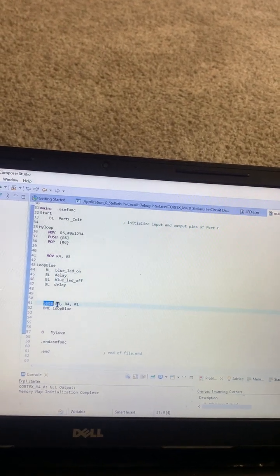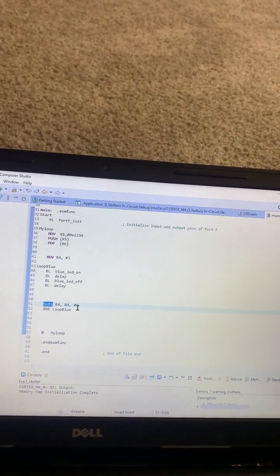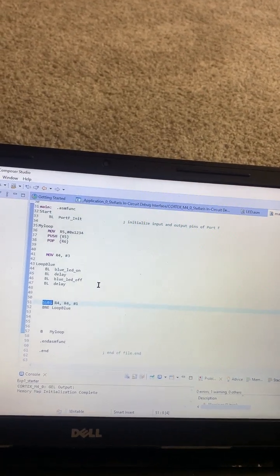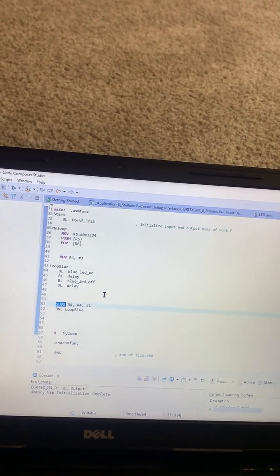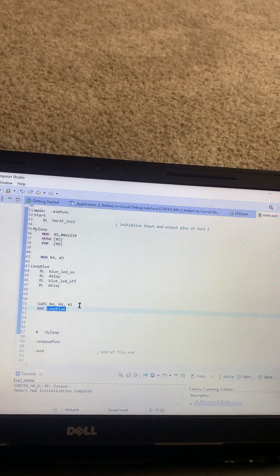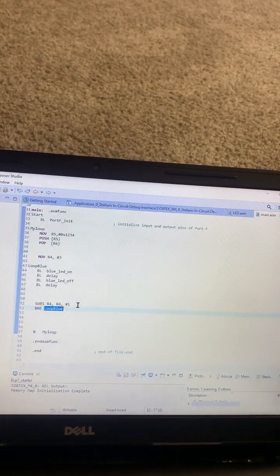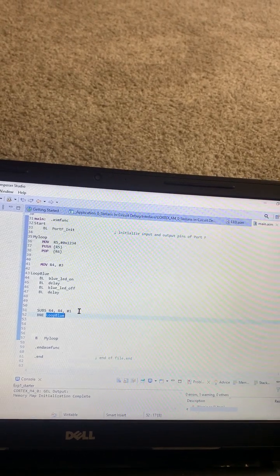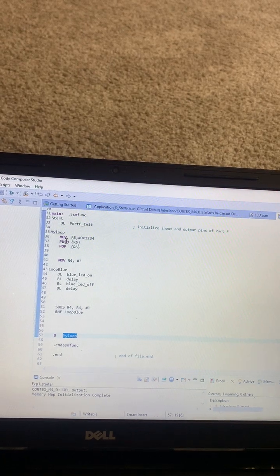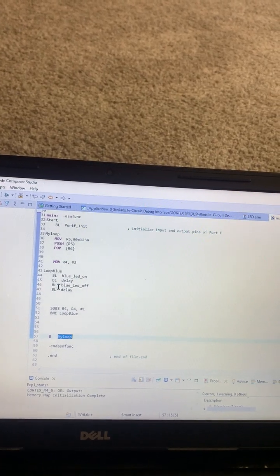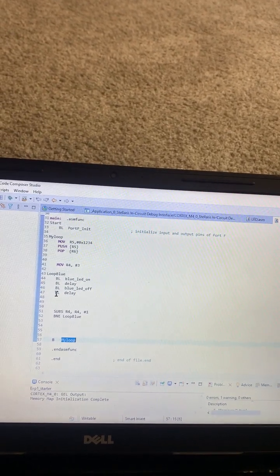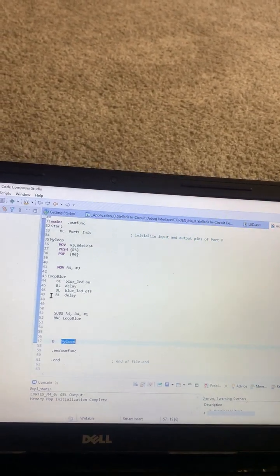Similarly, using the subtraction instruction, it will subtract 1 from the R4 register, which we previously initialized as 3. It then branches to loop blue until the subtraction result is equal to 0, and after that it will call the my loop function again and initialize R4 as 3. So it's an infinite loop running over, and later it's the end of the assembly code and end of line.